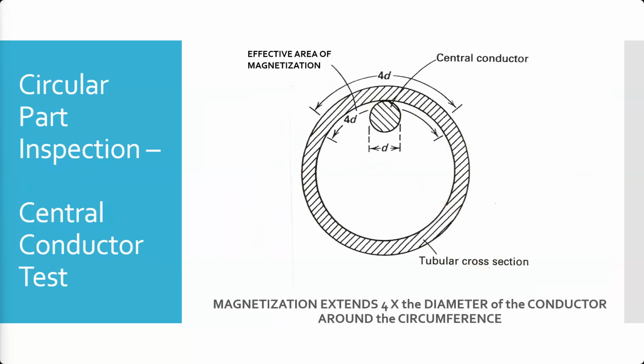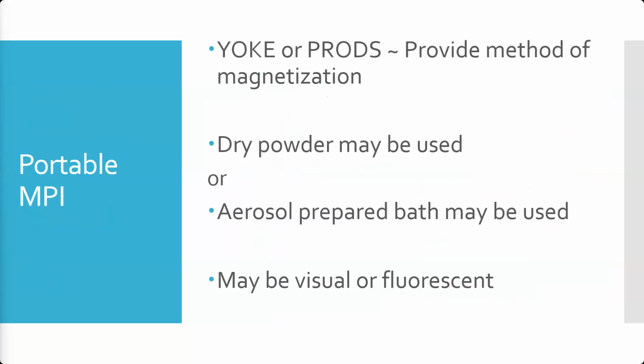But you typically want to use the largest rod you're able to fit within a part. If it has a bigger opening, we have different diameter bronze rods down there. And the larger the rod you use, the fewer times you have to turn that. Now sometimes what you get is a bigger gear with a very small central hole. You have to use a fairly small rod. There you have to rotate it quite a few times. So you just got to kind of keep that in mind.